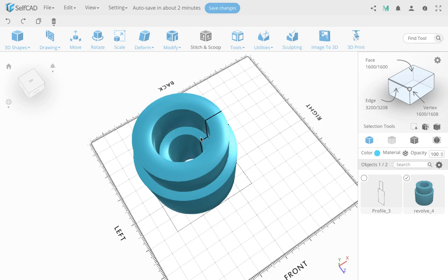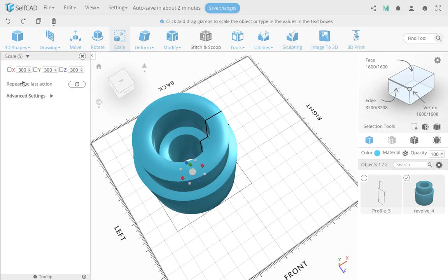I think 32 would also work in a basic circle. Depends, it's always different. But now you see we get, the number I reached happens to be a number that will do this in the measurement. And it's hard to know. Sometimes you just have to resize it after you do. And that's not specific to Revolve. It could be many other tools. But you see over here, we got the 300. This became 300 because it's a circular pattern, they're all the same size. So this is 300, and the Y hasn't been touched.